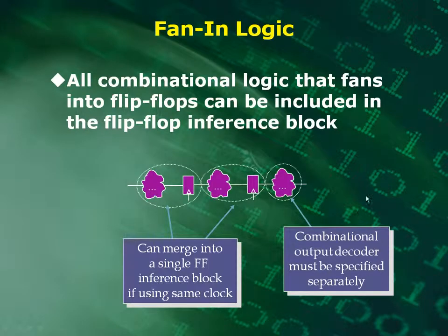Alright, we're going to start where we left off last time in the synchronous circuit stuff. And we're going to look at fan-in logic. All combinational logic that fans into flip-flops can be included in the flip-flop inference block. So I'll show you how to do that.